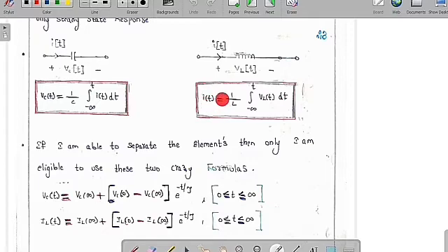So you can see clearly that I of t is going to depend on the past values of the voltage, and also Vc of t is going to depend upon the past values of the current. So we can say clearly that voltage is called the state variable for a capacitor and current is called the state variable for an inductor. Therefore, current cannot change instantaneously for an inductor and voltage cannot change instantaneously for a capacitor.